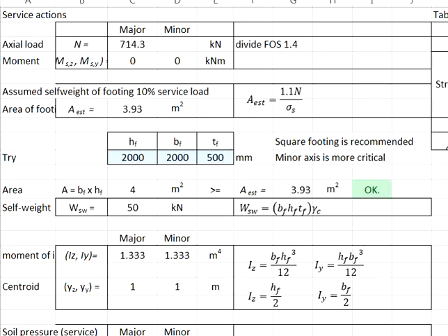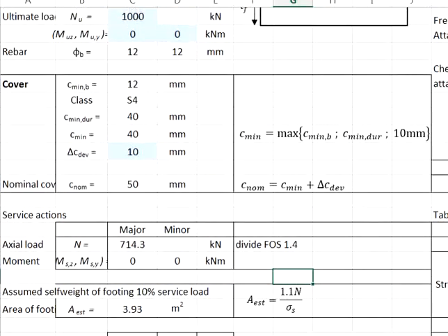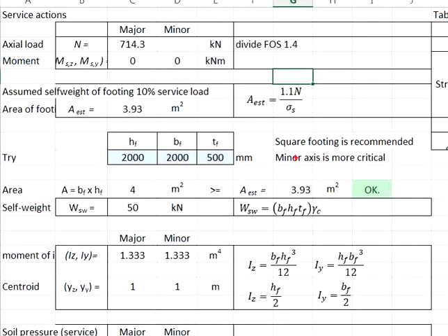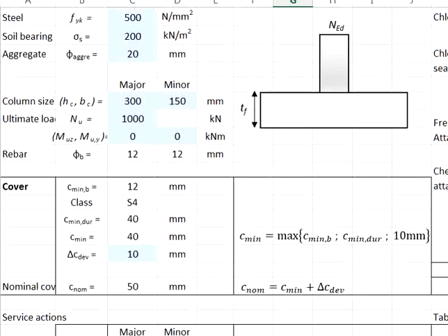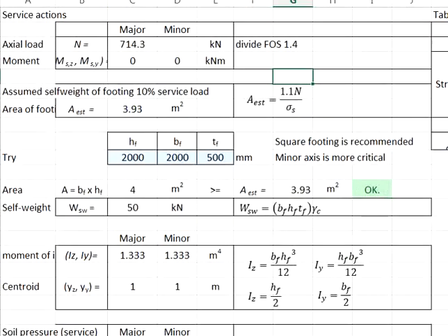For example, when you have adjacent pad footings too closely arranged with each other, in order to ensure sufficient working space, it might end up being a rectangular section. There is no restriction that you must have a square footing when subjected to only axial load. Of course, normally we will go for the square footing. This doesn't restrict the rectangular footing for such applications.